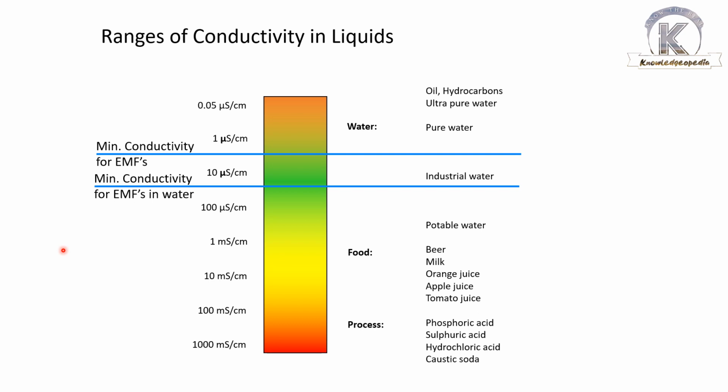And the third group is liquefied gases. These fluids cannot be measured with the EMF, but they represent only a very small part of all known and measured liquids. By far, most liquids are well above the minimum conductivity limits required for an EMF measurement.